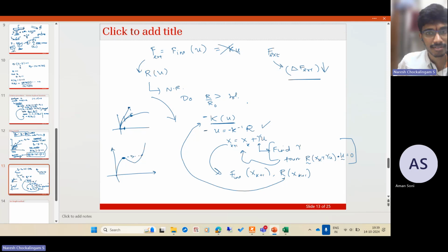If you want to do it faster, make the tangent approximate and make the line search accurate. An approximate tangent with line search will perform well. You'll get benefits in the computational time. If you use exact tangent and line search, it's not going to be very different from Newton-Raphson with a reduced load step.